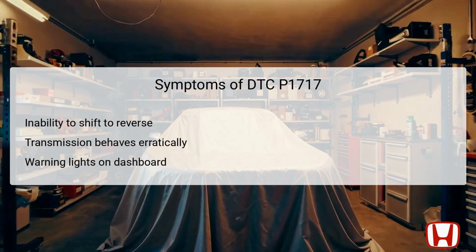Symptoms associated with DTC P1717 can greatly affect the driving experience and safety of the vehicle. A significant symptom is the inability to shift into reverse, which can prevent normal operation of the vehicle, especially in situations requiring parking or reversing.